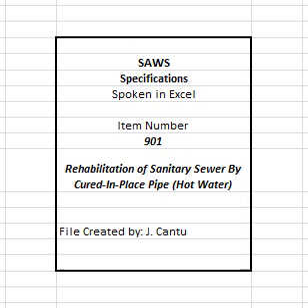The design calculations shall be signed and sealed by a professional engineer registered in the state of Texas and certified by the manufacturer as to the compliance of the manufacturer's material to the values used in the calculations. Review of the calculations by the owner or its engineer shall not relieve the contractor of any contractual obligations.